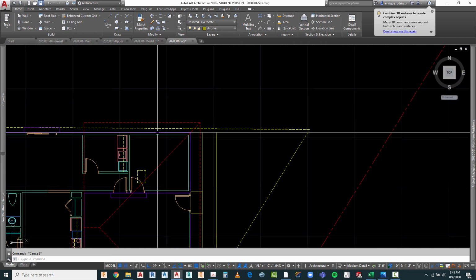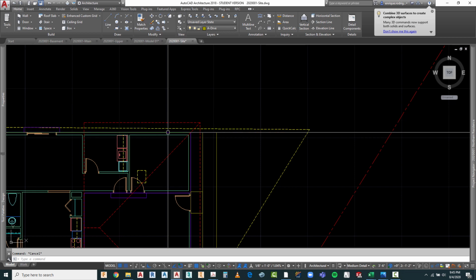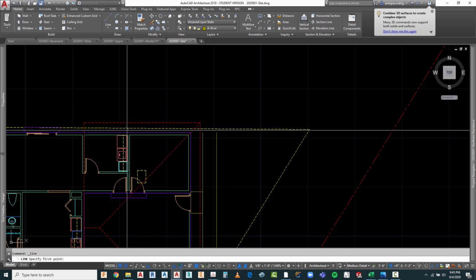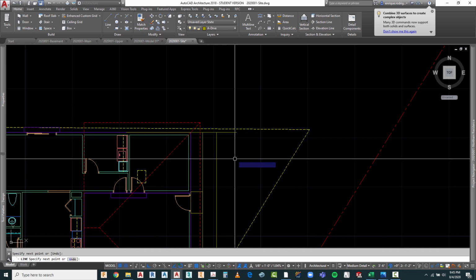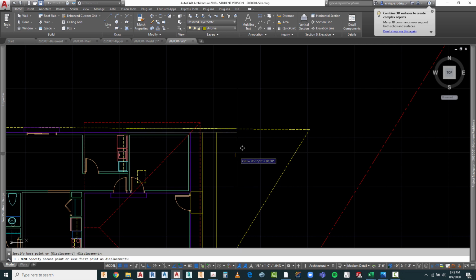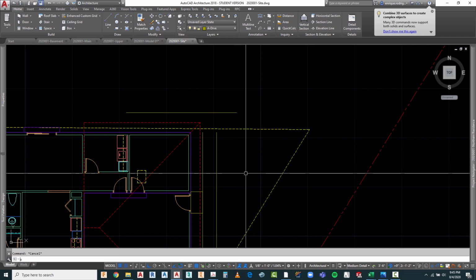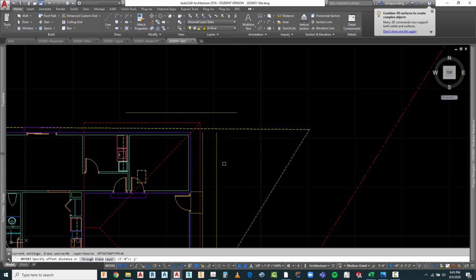And I'm going to go ahead and offset this a little bit more in the back, again because we have a window well located in there. So I'm going to go ahead and draw a line from here. And this one I'm going to go ahead and move maybe 4 feet back. Let's do 4 feet. I'm going to go ahead and offset this 3 feet.